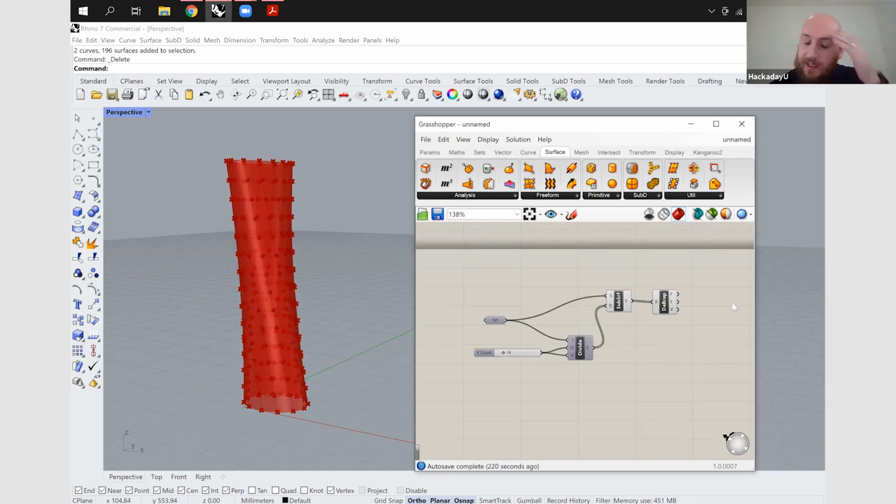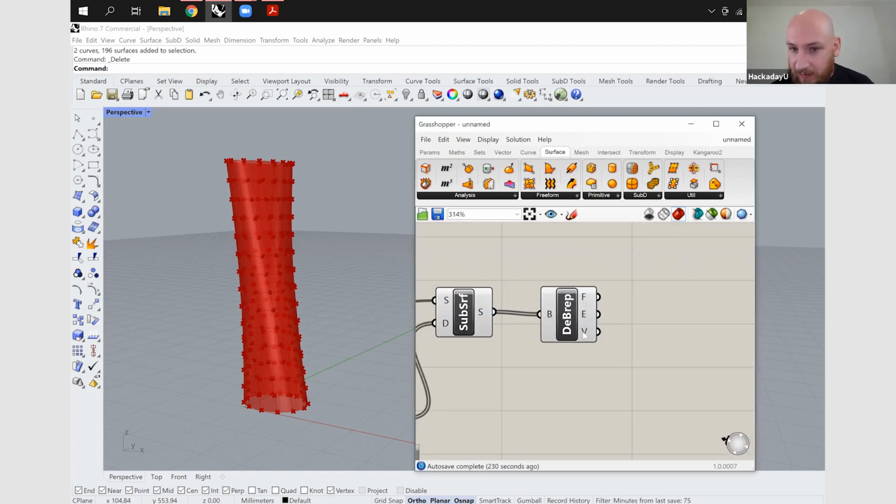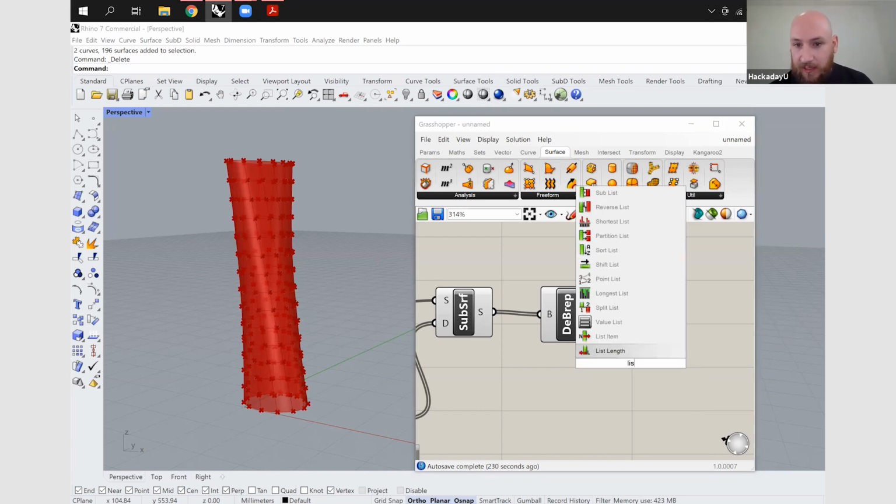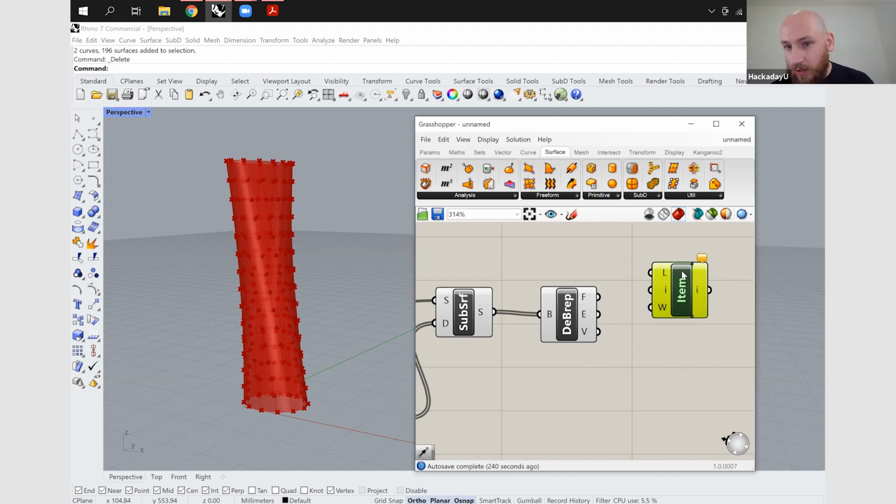So when I'm doing things in Rhino and Rhino modeling, I might just select points manually, but when I'm doing them in Grasshopper, I need a way of doing them sort of more computationally. So everything is in lists, and I kind of showed you the panel to see what's in that list. So I want to use the command list item, which says the number of the command. And each one of these lists is 4 points on each one of these cells.